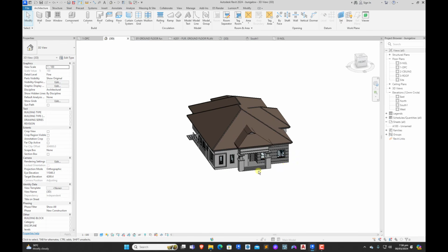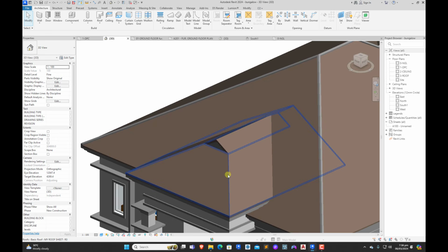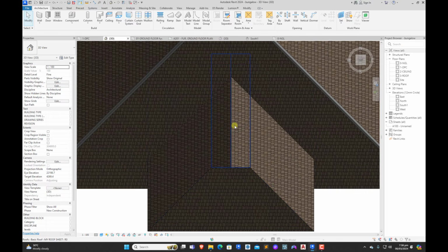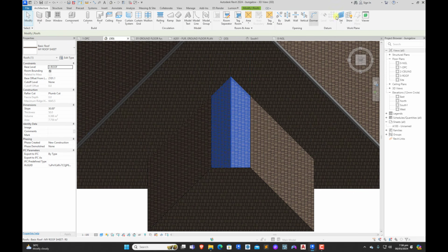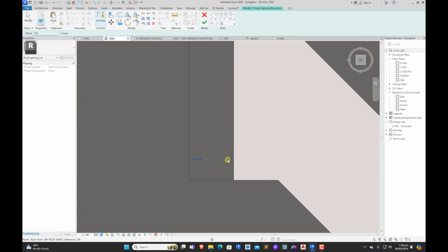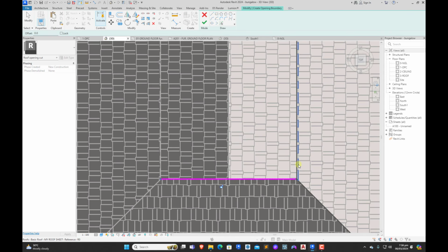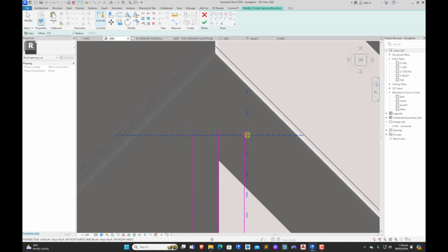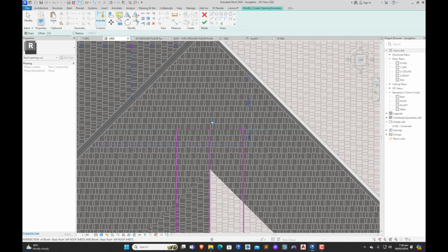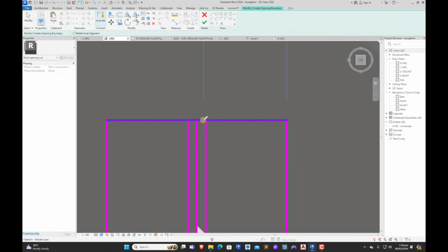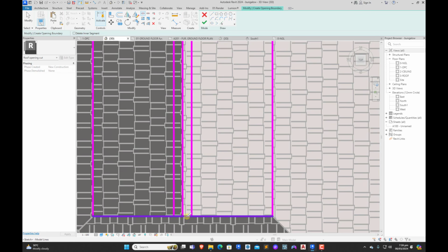You see. Now the next thing is for this last one. What we're going to do for this last one: you come to the top view as well. Click on the architecture, vertical. Click on this. Then you select this, and this center one. Then you also join them here. Offset here and here. Trim. You split this here, and you also split this here.